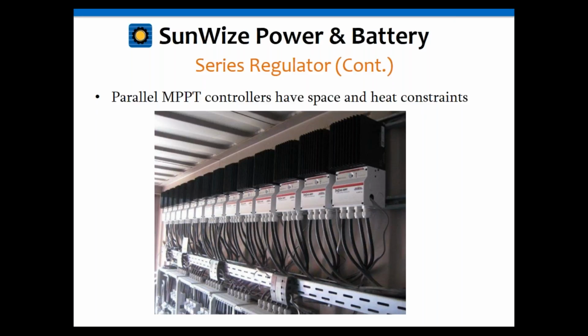And this is what happens when you try to do it with an MPPT or PWM type one. You end up having a whole line of these, and you can see the giant fins that have to heat sink all of that energy if you were to try to do it with some of the other types. So this works fine. You can do this, but again, this actually ended up being put inside a giant container because of that. And again, you have to get the heat out of that container because it's going to generate a lot. So just something to consider when you're looking at what type of charge control you might want to use for your application and why you might want to use one type over the other.